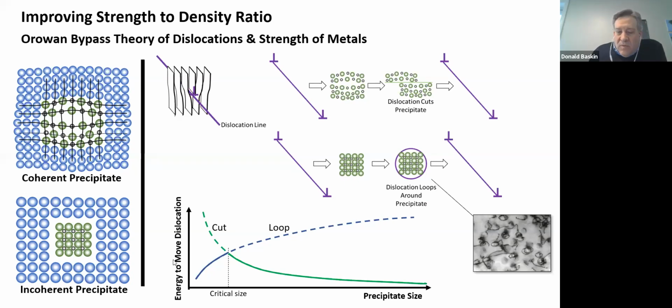So the net result is that there's a critical precipitate size right here where you get the maximum amount of strengthening. Okay, this is a really critical point. You have this piece of bread, you've got these raisins in it, you're growing the raisins. You're growing these raisins through tempering, or heat treating. There's a critical point where these precipitates get too big, they lose coherency, and you don't get as much strengthening out of them. Okay, so just try that again.